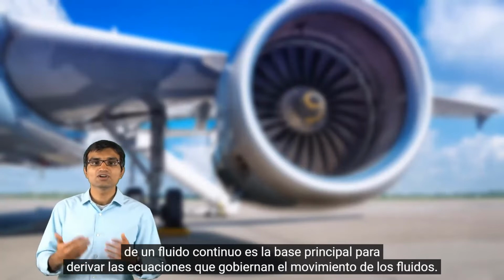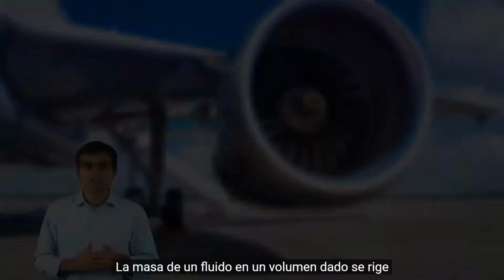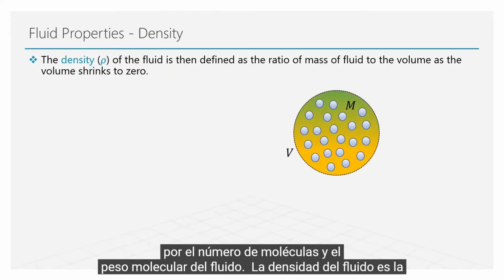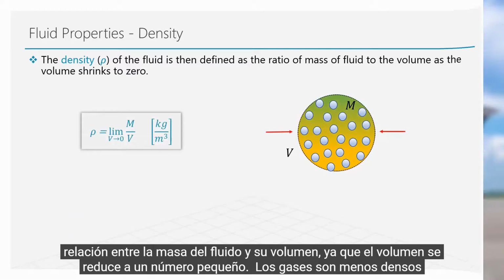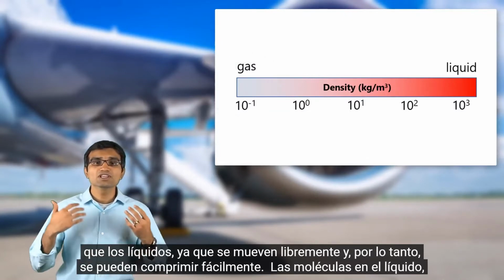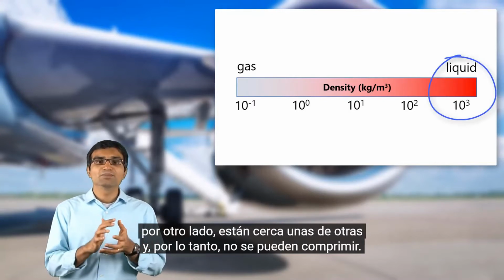The assumption of fluid continuum is the primary basis for deriving the governing equations of fluid motion. The mass of the fluid in a given volume is governed by the number of molecules and the molecular weight of the fluid. The density of the fluid is the ratio of the fluid mass to its volume as volume shrinks to a small number. Gases are less dense than liquids as they move freely and therefore can be easily compressed. Molecules in a liquid, on the other hand, are close to each other and therefore cannot be compressed easily.